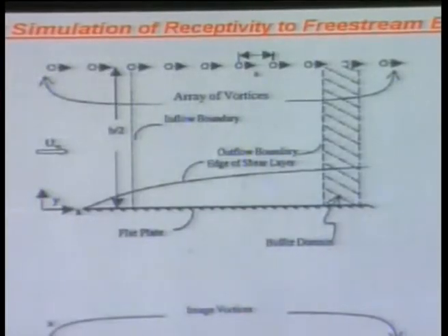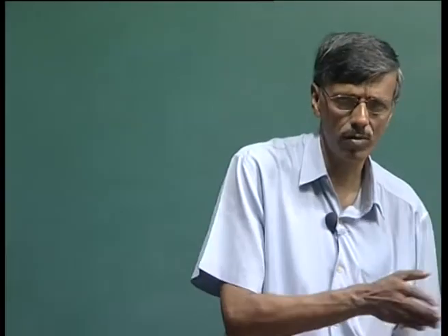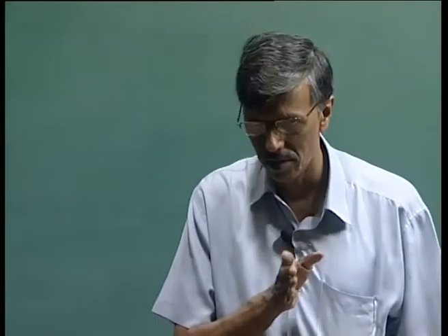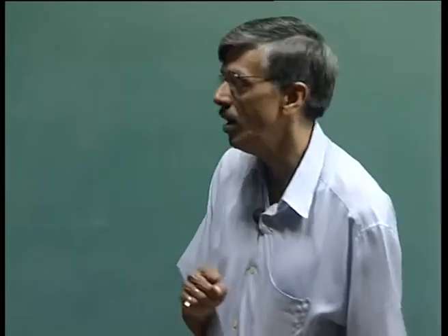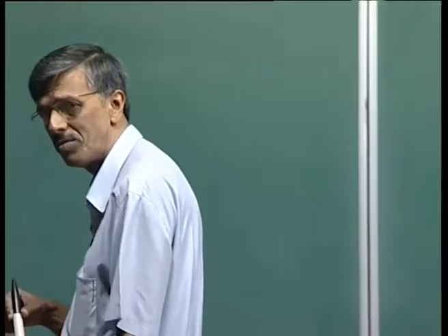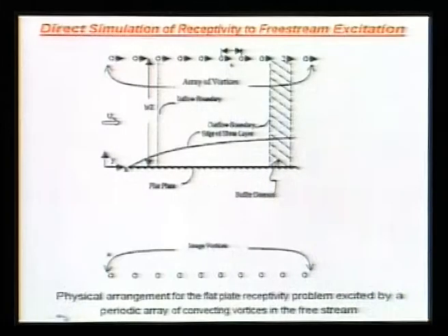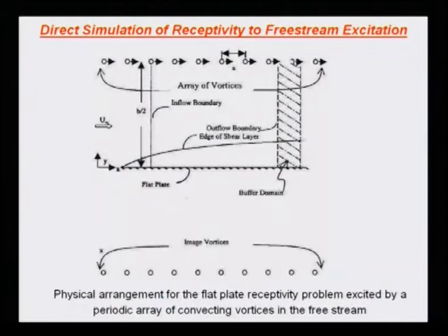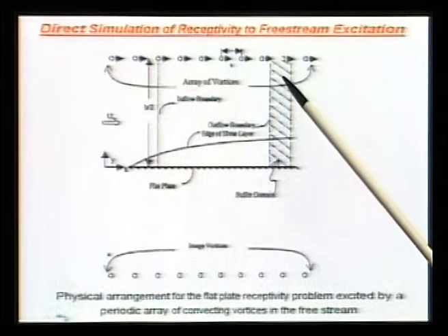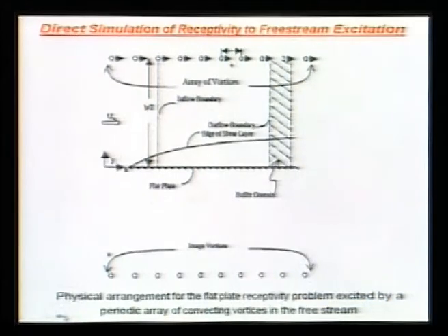The slip component does not create too much of a problem, because it is just going to give the existing fluid particle some kind of slip velocity. However, the normal component is potentially dangerous, because that implies as if there is some kind of mass source here, which should not be there because we are not explicitly adding any mass source. To obviate that conceptual violation of mass conservation, we can immediately talk about an image vortex system.